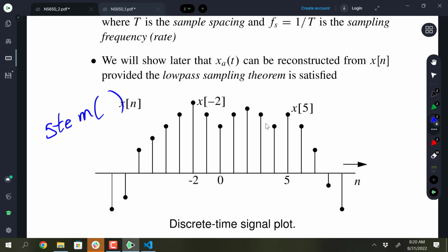But the idea of connecting dots would be simply linear interpolation, if that's how you choose to connect the dots, and that's a special type of signal processing operation that we'll talk about when we do upsampling followed by an interpolating filter. So it's not legal to say there are values in between those samples in a discrete time signal. They're certainly not stored on the computer, and for you to plot it that way can be misleading unless you are clear on what you're doing with that.